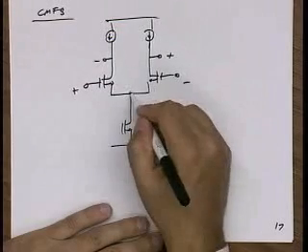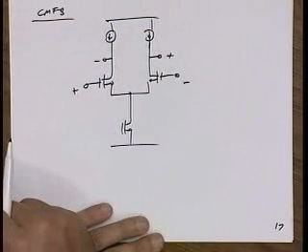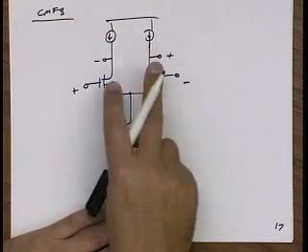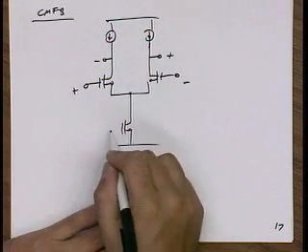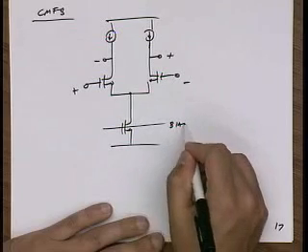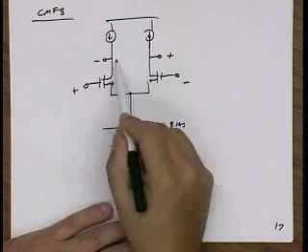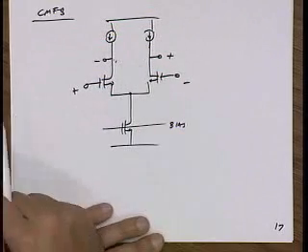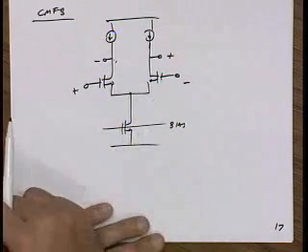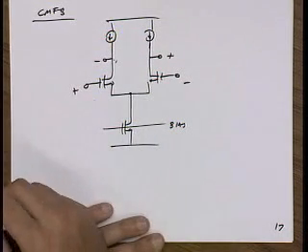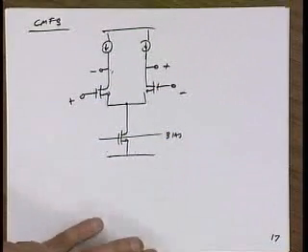And the reason it will not work is that if you build it, and then you go and measure it in the lab, without common mode feedback, what are you going to observe at the output? It's going to be either at VDD or ground, right? So why is that? Why is it that this thing doesn't work?